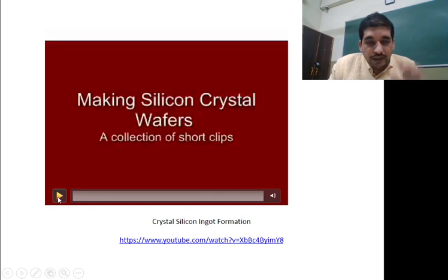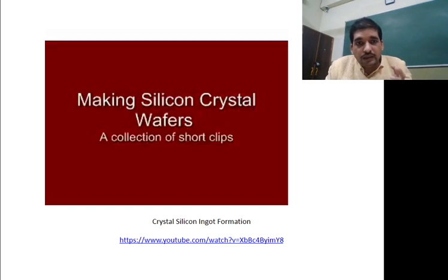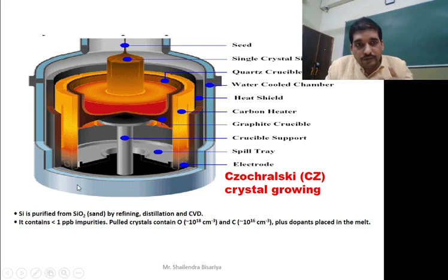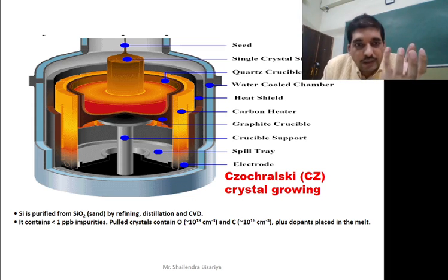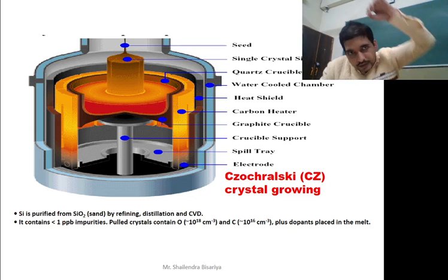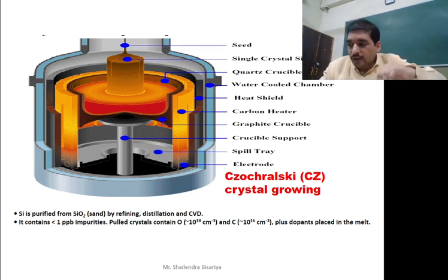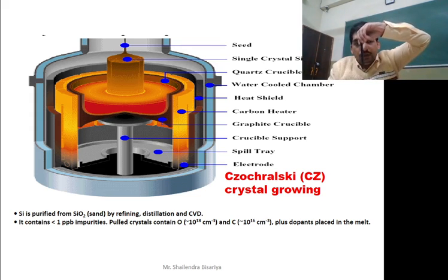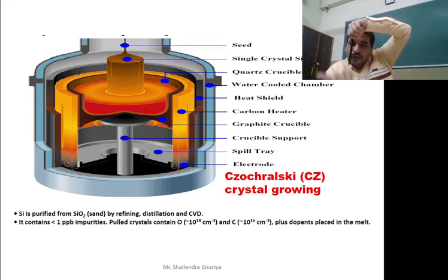As we have already seen the structure, you can visualize that structure. Let us first see this picture: this is basically the crucible, and inside the crucible the material is in a melting state, and outside the crucible there is the crucible support, right? The seed crystal comes inside and touches it, and it is rotating in one direction, and the crucible is rotating in another direction.